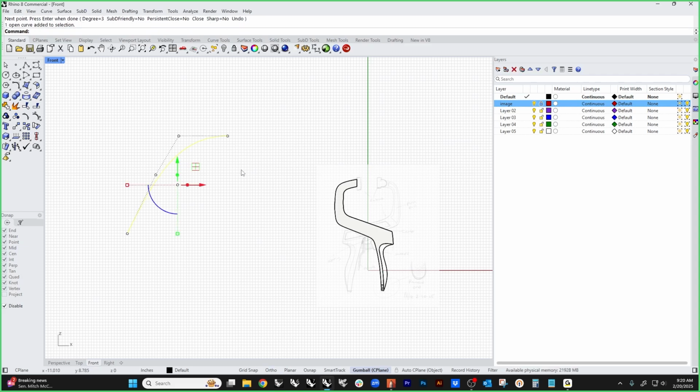If we take this curve and I mirror it, and I look at the points for both of these, this is your welcome to continuity TED Talk here. All right. So positional continuity, or G0, is considered these 2 points right here from this curve and this curve. If I move these apart, there's a point there and there. Up here, 2 points, but they're coincident. They're on top of each other. That's G0. That means the curves are touching. That is positional continuity.